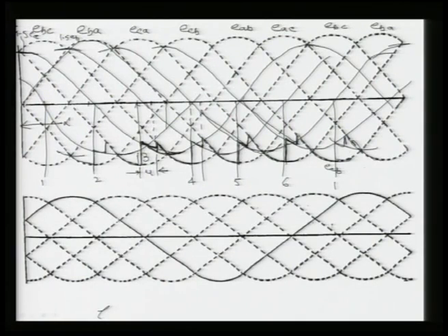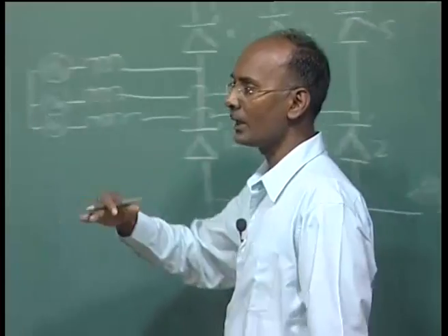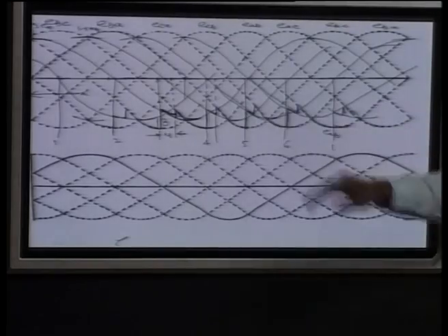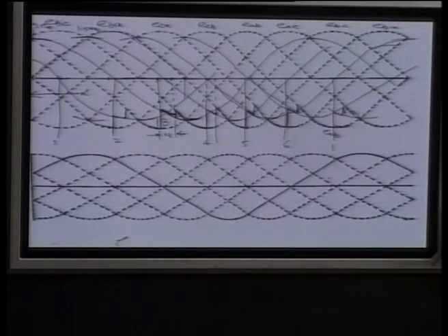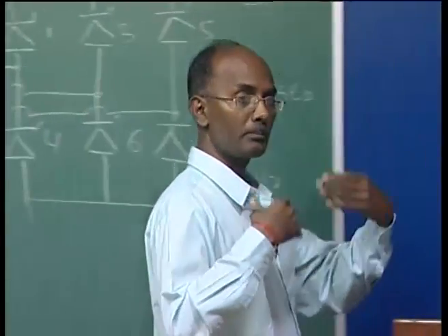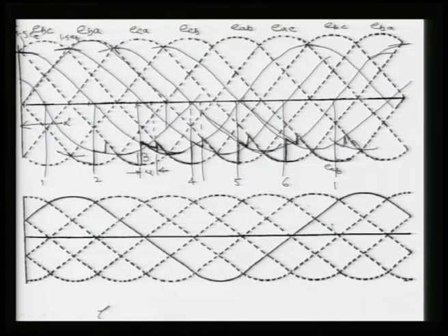So, this is your output DC voltage, and you can see it is the negative side. So, average voltage will be negative, and now it is working in the inverter operation. Now, again to draw the valve voltage, you know the valve voltage will come on the positive side, and you can see again we can start here from the 3. Once you have given the 3 here, means 3 will conduct till here. Now, this 3 is conducting.